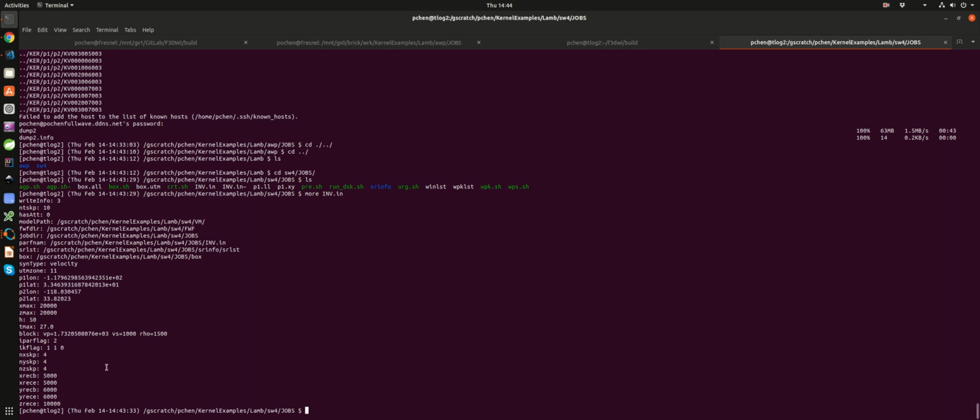So the grid spacing is uniform, 50 meters. I also tried a few different configurations with the SW4 refinement command, but the results were pretty much similar, so I didn't actually use a composite grid. Here inside of SW4, I'm just using a uniform grid, and then there are a few new capabilities that I added to the code.